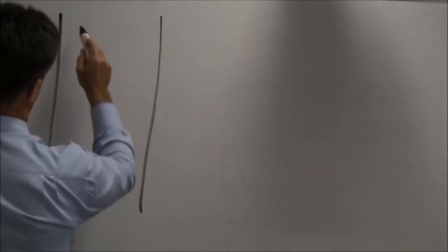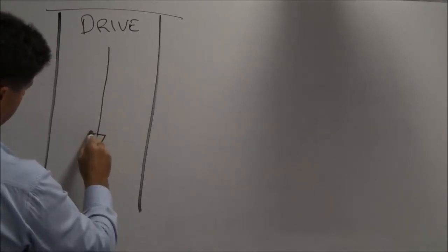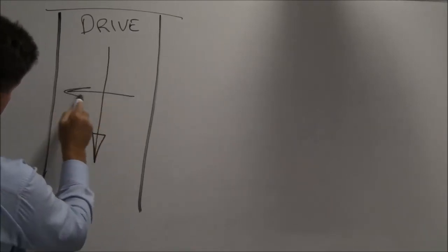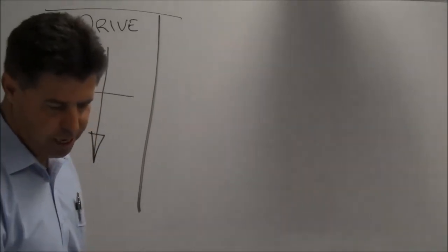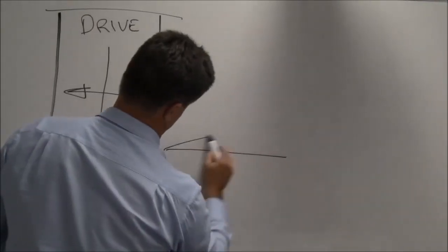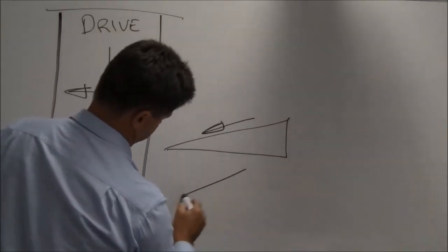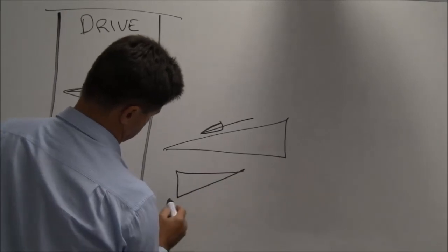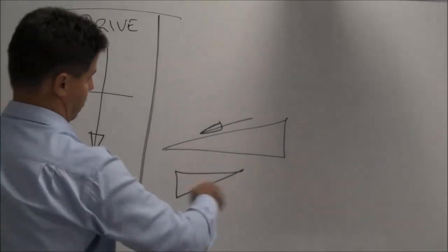So, if that's my driveway, I have fall that way, and I have cross fall that way. Someone sent me an email and asked me why do I add the two together. The area of the triangle, so that's our fall longitudinally, and we then have cross fall across the driveway. So there are two different areas that we need to calculate. We can't just go and multiply the whole thing together.